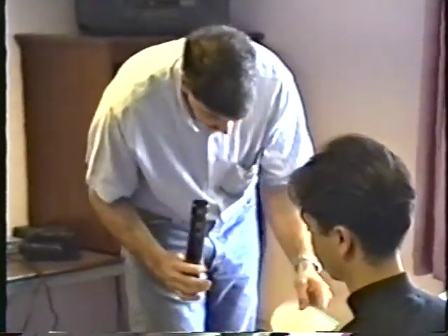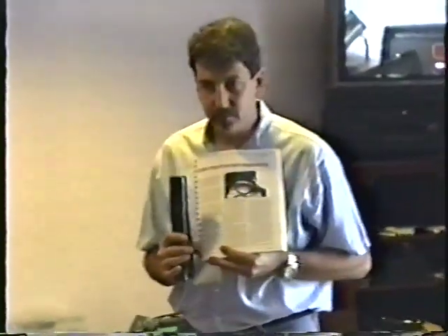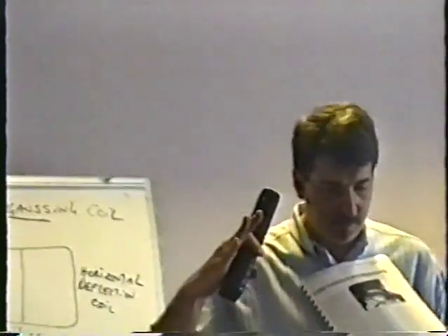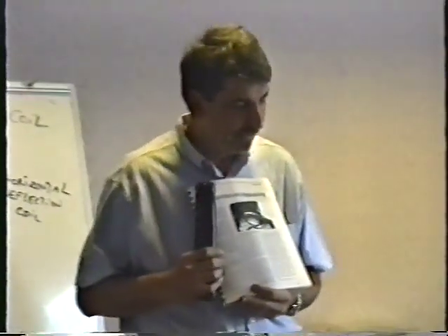So you can get a degaussing coil. If you turn in your book, I think it's page 61. God, look at that, I turned right to it. On page 61, you'll see a picture of this degaussing coil here. This small coil right here. Well, it's not that small. It's actually about this big. And they're about $40, and you can degauss the picture tube manually with that.